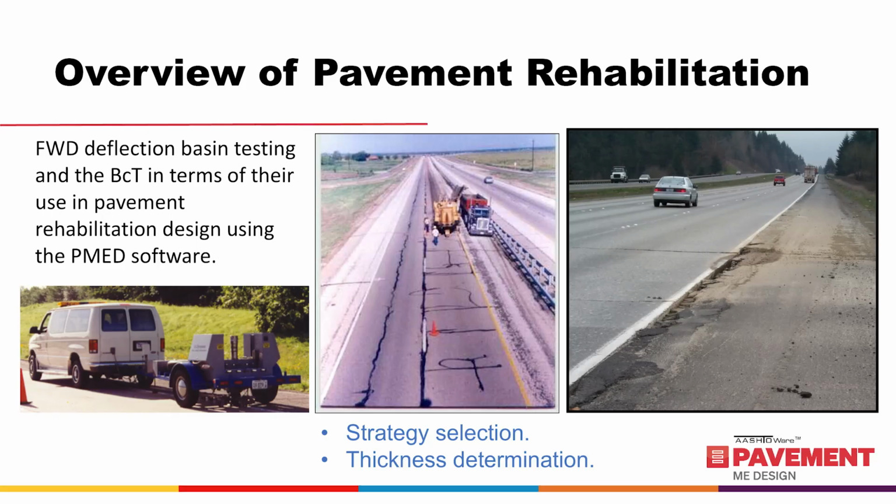Module 3 focuses on the structural condition of the pavement itself and not the adjacent features, but the condition of the adjacent features should be used in selecting an adequate rehabilitation strategy. For the structural assessment using FWD testing, the types and causes of the distresses should be defined.